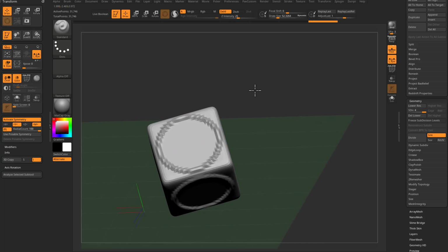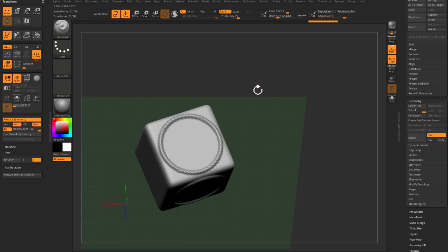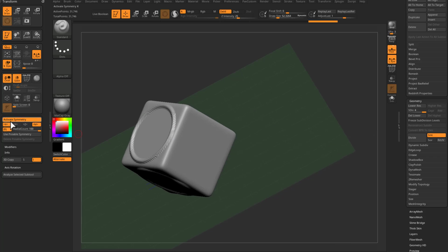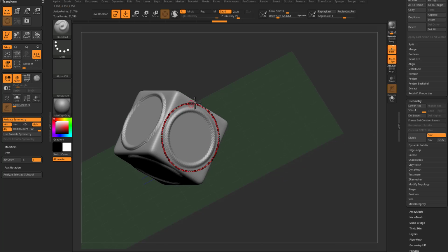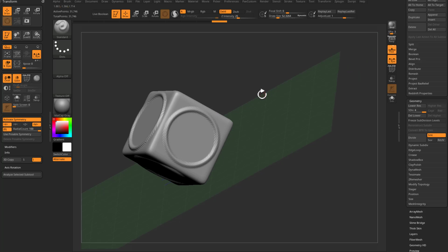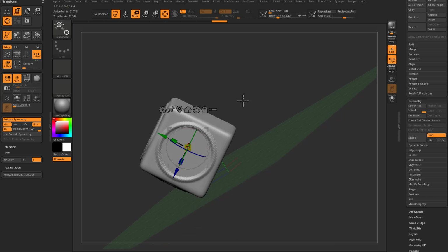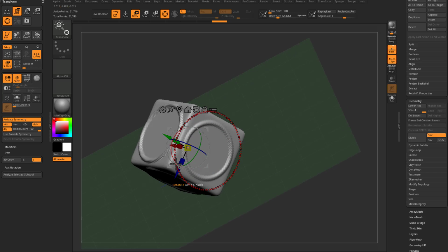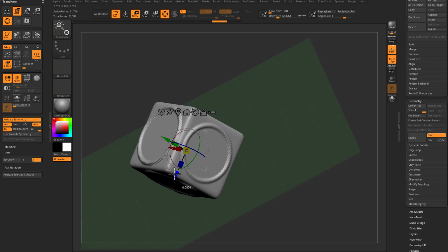So now when Z is down here, this is the Z direction, I can change it to the Y direction, and I'm right here. Now one thing you couldn't do in the world axis without moving the object anyway, is be able to control where this pivot is. So if I turn on the x-axis here, and I'm sculpting, again, it's converging at a single point. And guess what? That single point is wherever my gizmo pivot is. That tells it where the center of my radial symmetry is. So if I move this forward, it's going to move my whole object.